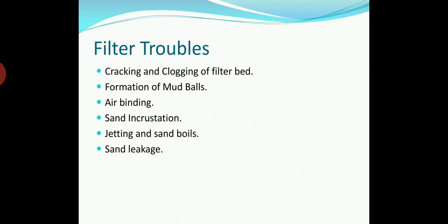The separation of this dissolved air may be due to the following reasons: the negative head due to excessive loss of head, increase of temperature of water, release of oxygen by algae. Avoidance of excessive negative head is done by providing a water depth of at least 1.5 meters.